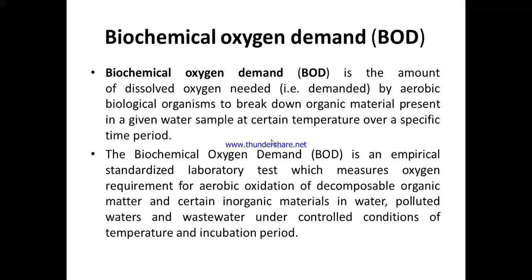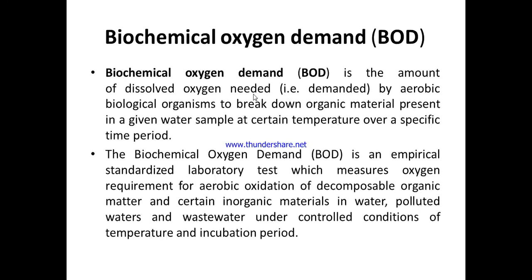So basically students, biochemical oxygen demand is the total quantity of oxygen required for oxidizing the organic matter present in the wastewater by the aerobic bacteria and other microorganisms that require oxygen. So it has been written, biochemical oxygen demand is the amount of dissolved oxygen needed by aerobic biological organisms to break down the organic material present in a given water sample at a certain temperature over a specific time period.